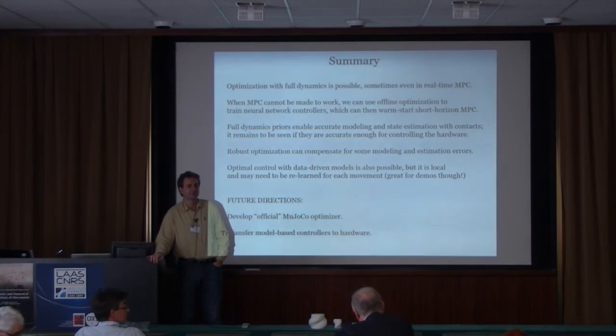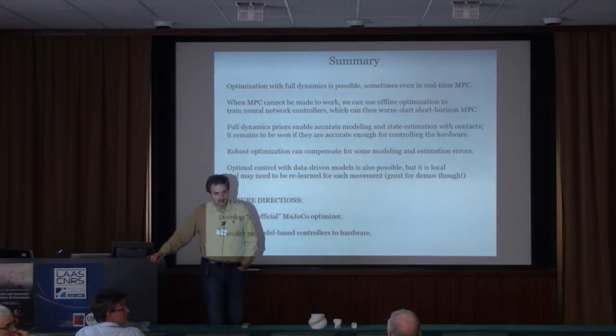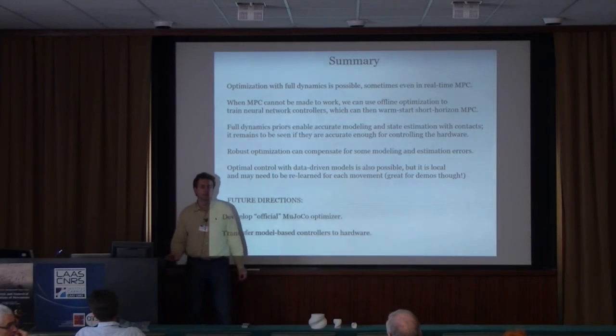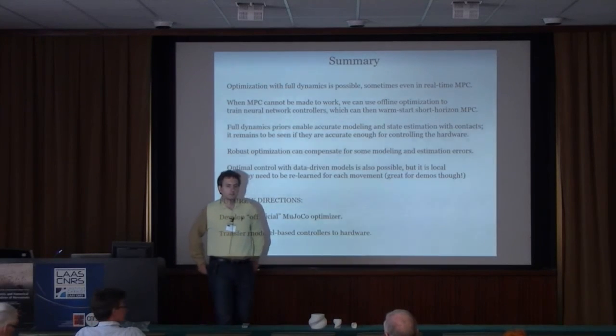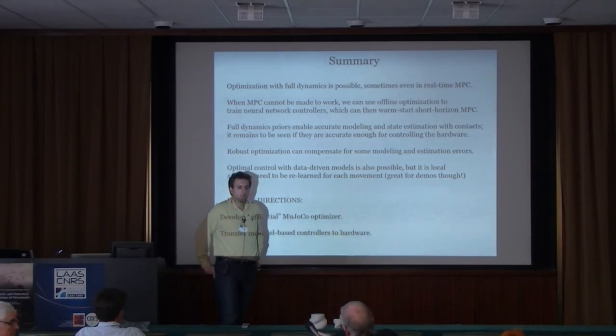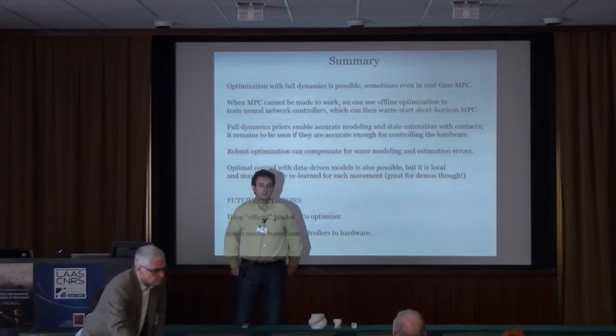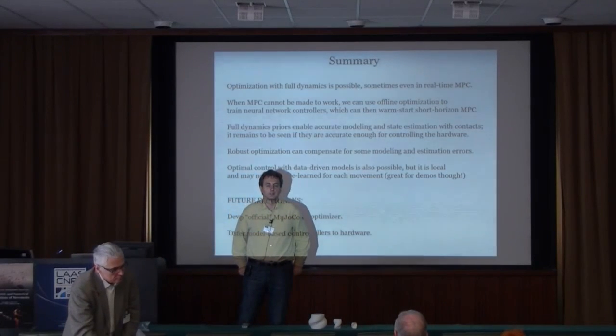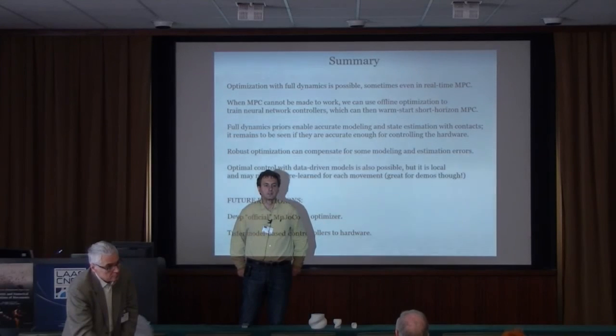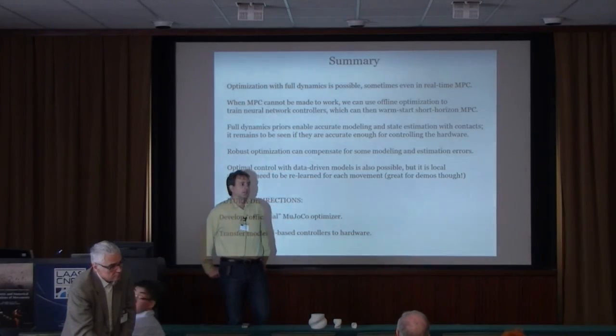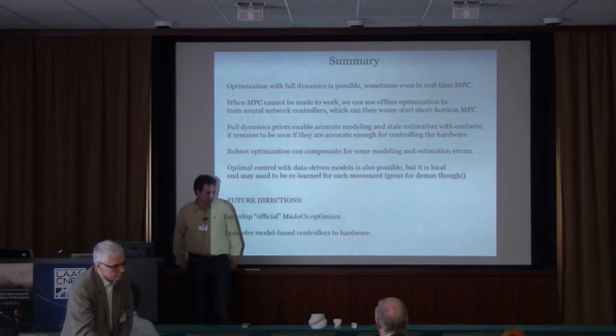Thanks, Emo. That was very impressive as usual. I'm not sure I fully understand the contact-invariant optimization. Can you include in that properties that I'd like to have at the contact point, like say passivity? Passivity, what exactly do you mean by that? Passivity meaning that I can take the system and wiggle it around any way I want, but I can't get any energy out of it continuously. That's key to establishing contact stability and so forth.